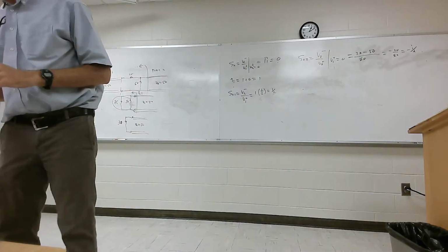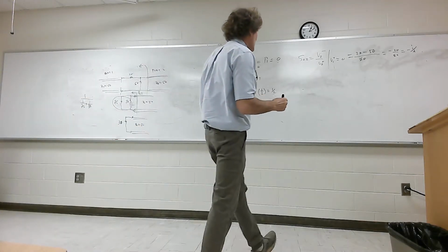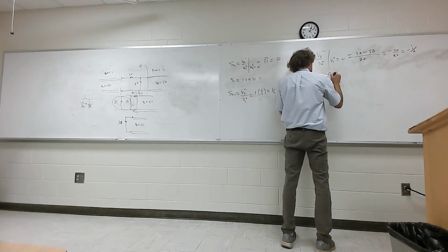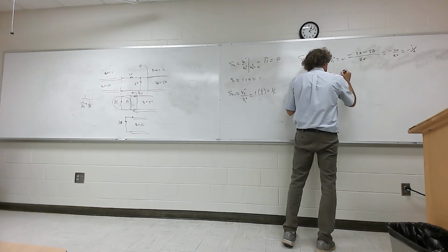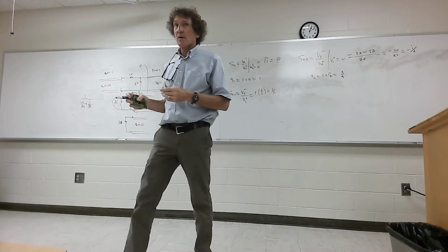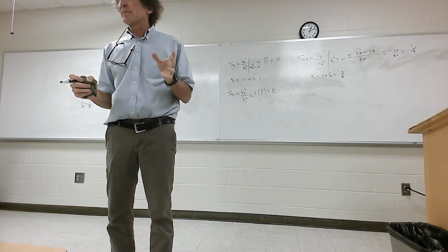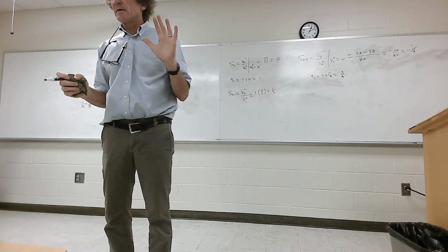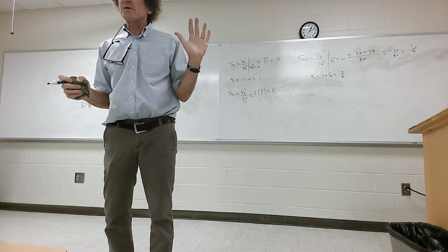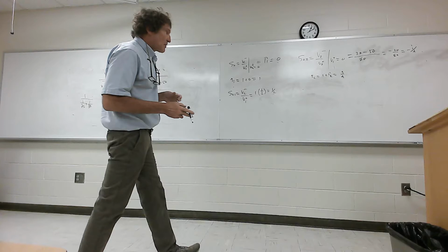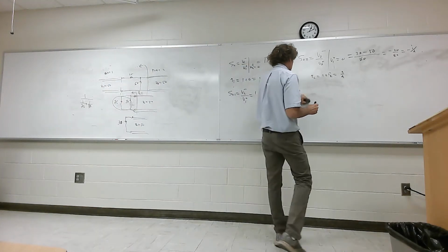Okay. Now, I'm going to go ahead and get the transmission coefficient from port 2, and that would be 1 plus reflection coefficient 2, which is going to be simply 3/4. Y'all follow me? All right, convince yourself that that's correct. Y'all got the reflection coefficient, right? It shouldn't be a problem. You guys should see this fairly easy. It's simple resistors.